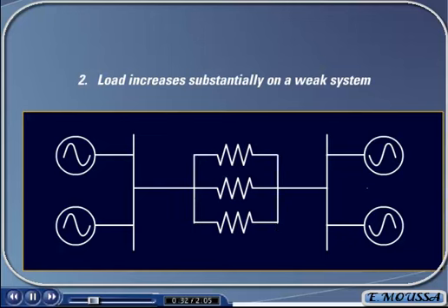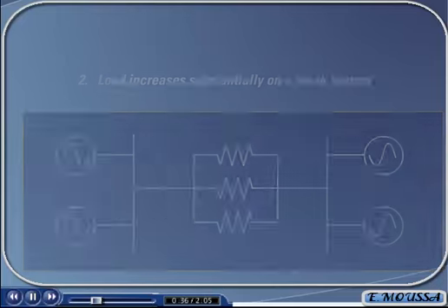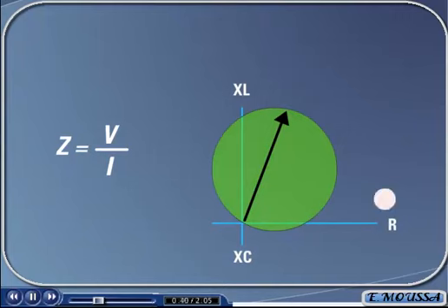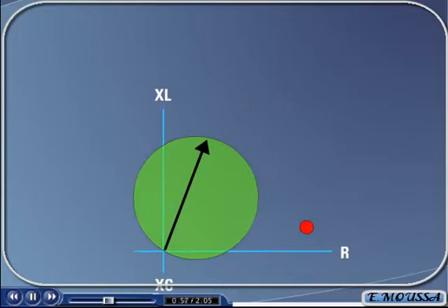During a power swing, the voltages and currents will fluctuate significantly, drastically affecting the value of the measured impedance of the line. The plotted impedance as measured by the distance relay will slowly swing from our load point into the distance operating zones, and then back out to a load point if the system regains synchronism. The power swing blocking feature on advanced distance relays can detect that the impedance swing is a recoverable power swing, and will block the distance zones from operating.